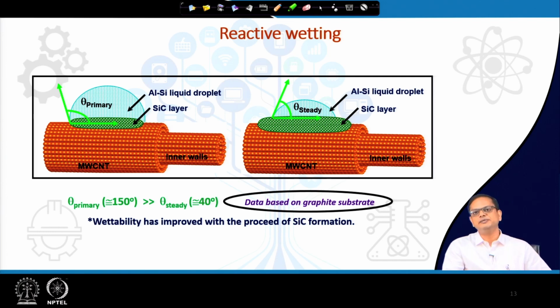As I mentioned earlier, if we have carbide layer growth at the interface, because of its brittle nature, the crack propagation starts from there. Okay. But in this case, if you have only few nanometer layer of SiC, that will be giving some kind of bending ductility, and it will not really be fracturing that easily.